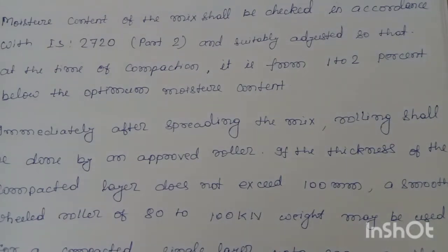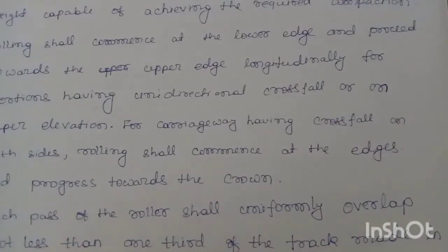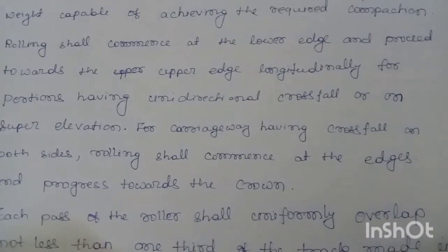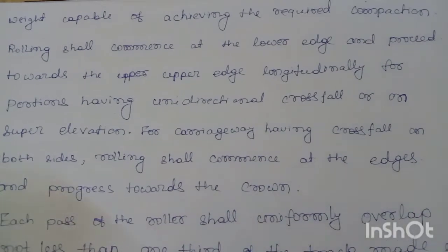For a compacted single layer up to 200 mm, the compaction shall be done with the help of a vibratory roller of minimum 80 to 100 kilonewton static weight capable of achieving the required compaction.